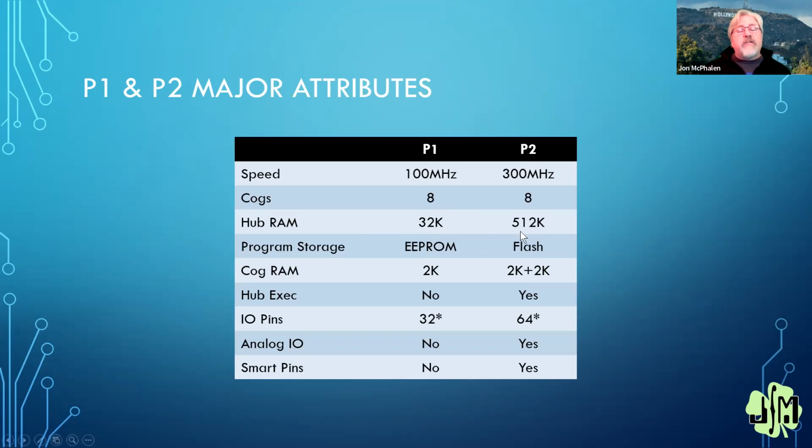Flash is very fast. Now, there is a tiny bit of a downside: we don't yet, that I'm aware of, have a nice flash driver that we can use any way that we want. Flash is a bit different. With an EEPROM, we can just write to any individual memory location willy-nilly without worrying what's already in it.